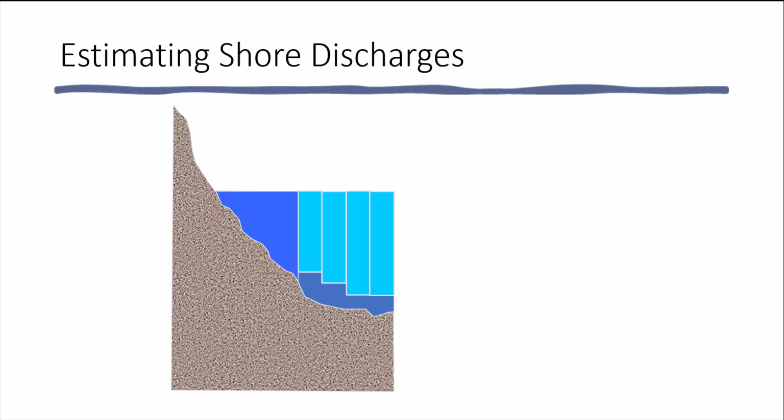It is recommended that when the depths near the shore become too shallow for two good bends, the transect be stopped and the discharge in the edge estimated from the available data. So what information is available? The ADCP has the depth of the last ensemble and the velocities in the last ensemble.